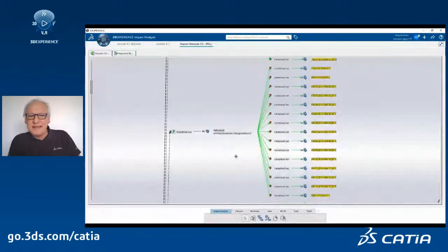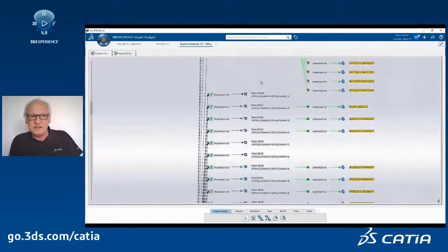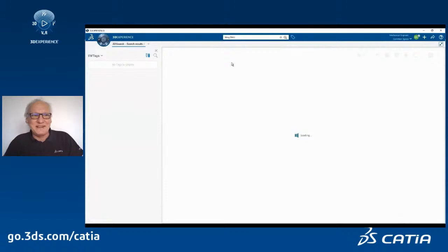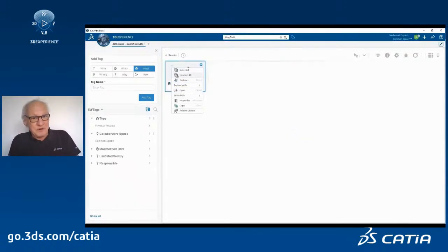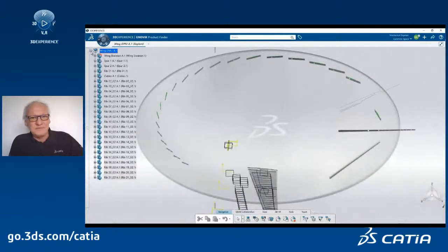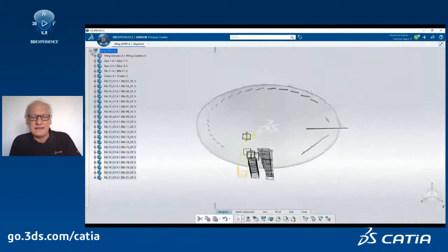And now we'll see how the mechanical designer is taking into account this design change in his job for the ribs. Okay, so I'm back as a mechanical engineer. I will search for my wing DMU. I will explore first to see what's happening. First sign, I see that the wing skeleton is double locked, okay? Both instances and references. Something has happened.